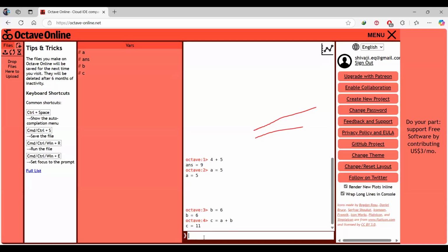Like I can tell you, let's say W is equal to 4 kilonewton per meter, and my span is, let's say, 6 meters. So my bending moment comes out to be W L square by 8, if I'm having a simply supported beam. So it is telling me a bending moment of 18 kilonewton meter.